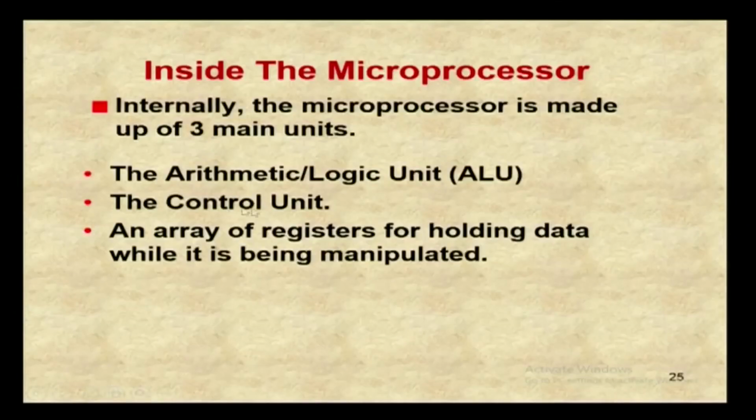It has to decode the instruction and tell the arithmetic logic unit whether to add, subtract, shift or multiply and so on. So the control unit generates all the control signals. It has to tell when to read the memory, when to send the data to the output unit, and all those things.